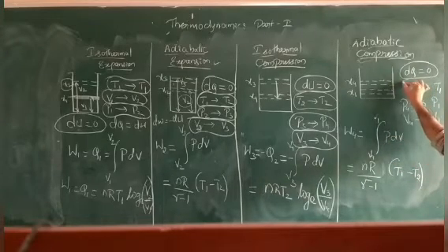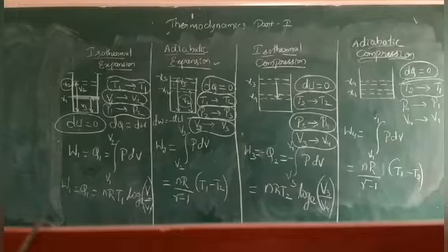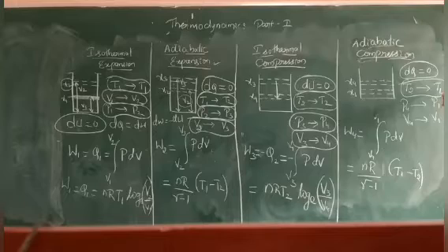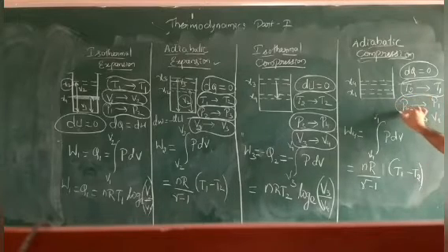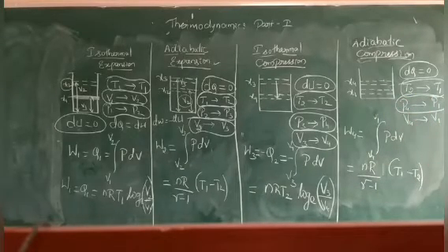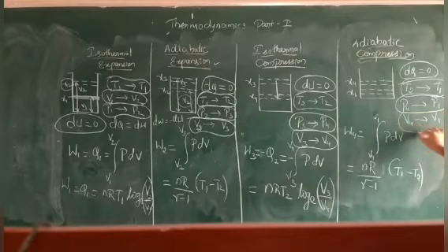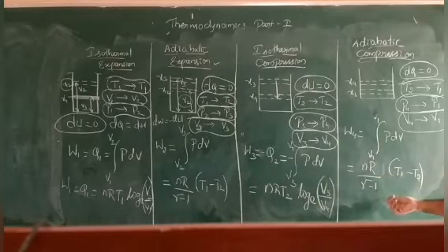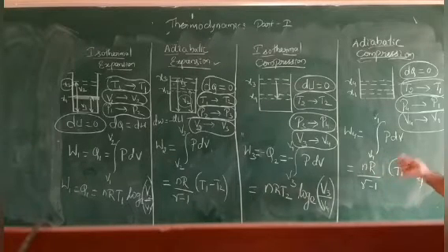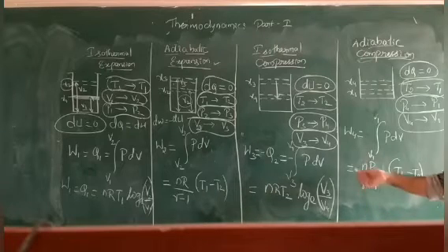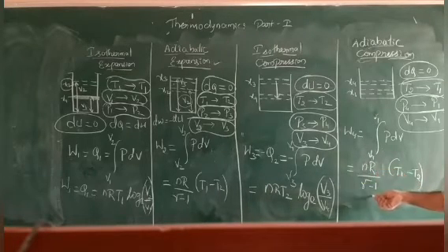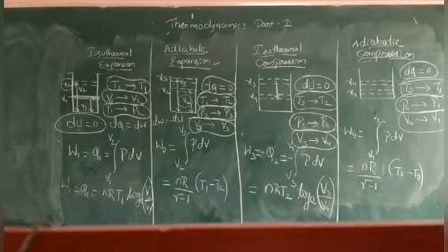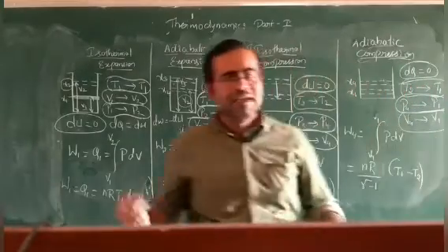When we have dq value 0, that is adiabatic, the temperature should not remain constant here, so it is changing from T2 into what here? T1. So observe the variation from T2 to T1. Now the pressure is changing from P4 into P1, and the volume is changing from V4 into the original volume V1. So again you observe adiabatic compression, so that we can observe a total amount of work done, nR divided by gamma minus 1, again multiplied by T1 minus T2. So these are the steps you are going to observe in the Carnot engine.